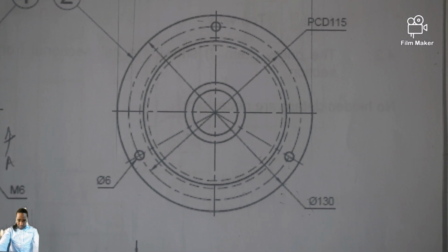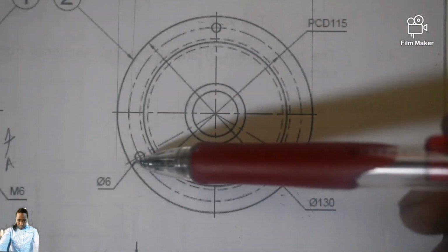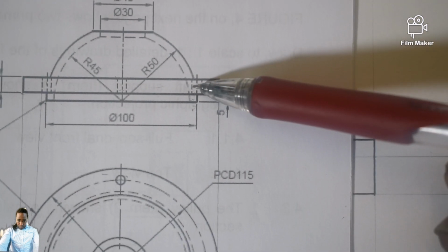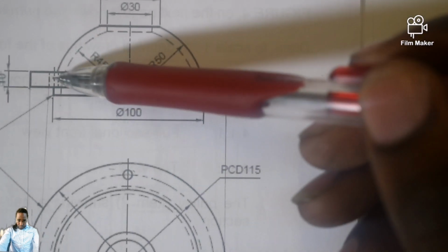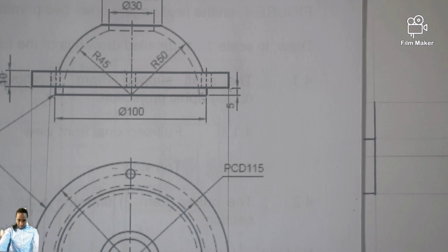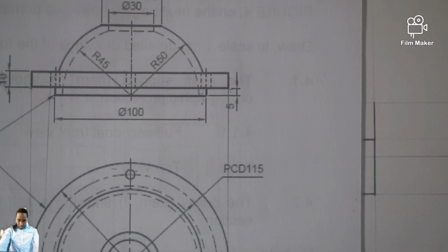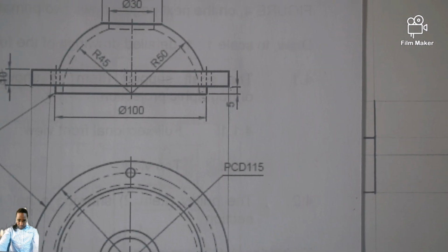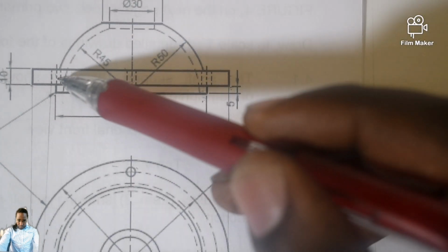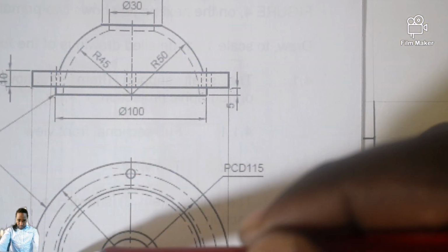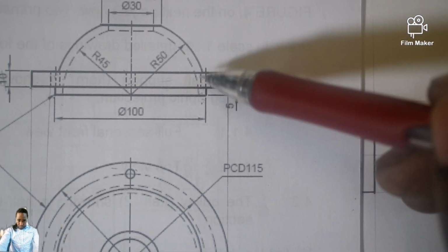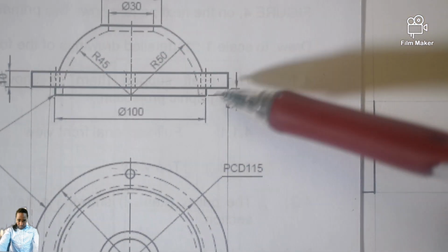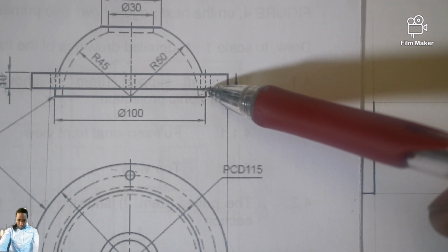So I do not even have to bother drawing this one. Again, this one from here till there will disappear. This is the center. Even the center we won't draw, because we draw a center line to symbolize that there is a hole beyond the surface that you are putting hatches at, and that is in line with what has just been cut or has disappeared. You understand? So 1, 2, 3, they will disappear. This one is the PCD and it will disappear. This one disappears. From here till here, this line of yours will disappear as well.